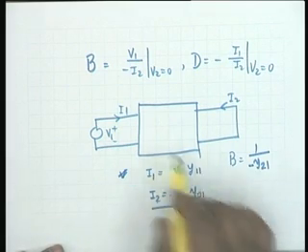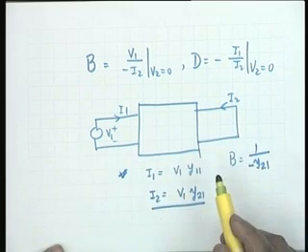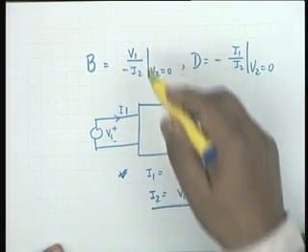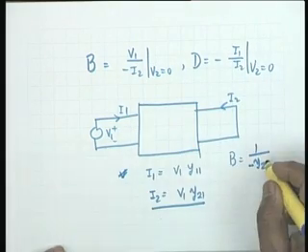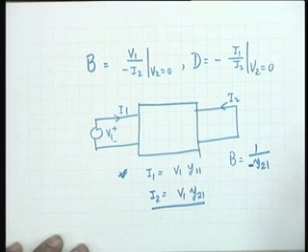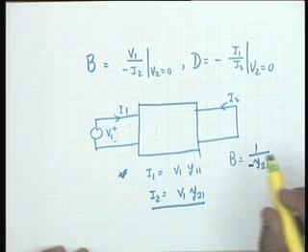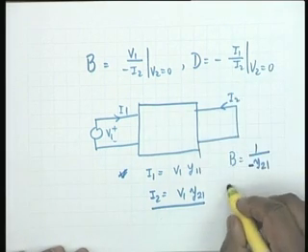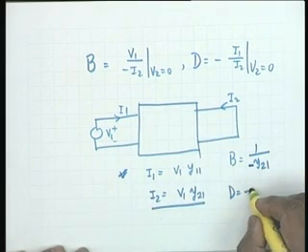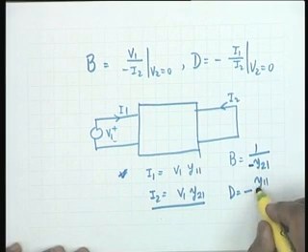You see, this is the relation for this situation. Okay, I2 equal to V1 y21. So, V1 by minus I2 will be minus y21. Do not forget this negative sign, it is extremely important. It will make a mess if this is not included. And as far as D is concerned, for D you simply have to take the ratio of the two with a negative sign. So, D would be minus y11 divided by,